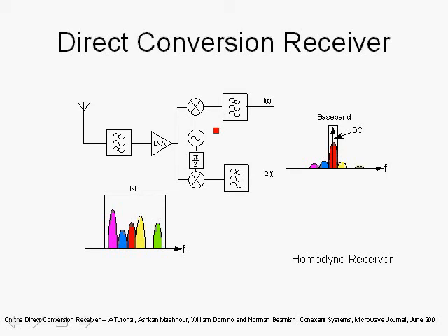In a direct conversion receiver, the IQ imbalance is even more pronounced because in a heterodyne type receiver, most of the gain is done before the down conversion to baseband, but in a direct conversion receiver, after you down convert to baseband, you go through multiple gain stages, and these gain stages can exacerbate the IQ imbalance in the gains. Also, a big problem with direct conversion receivers is DC, and the DC can be amplified by the high gains in the baseband analog chain for the I and Q channels, and that can also cause an imbalance.